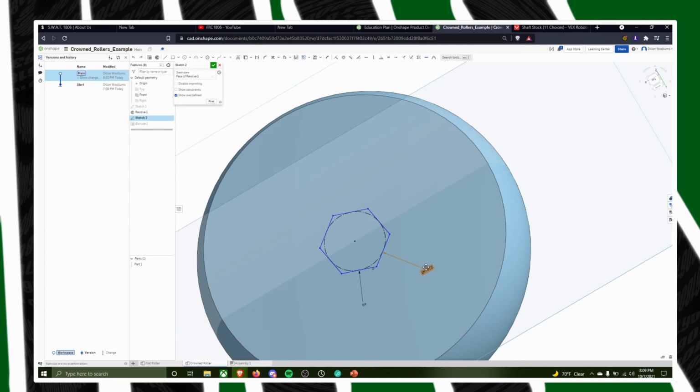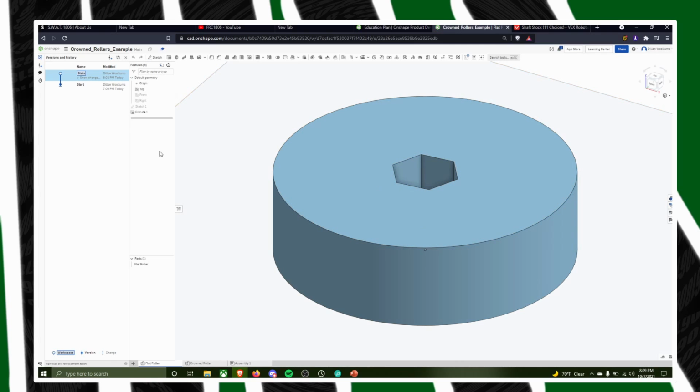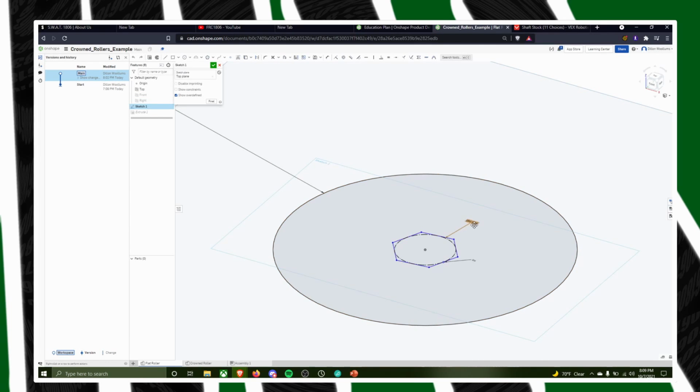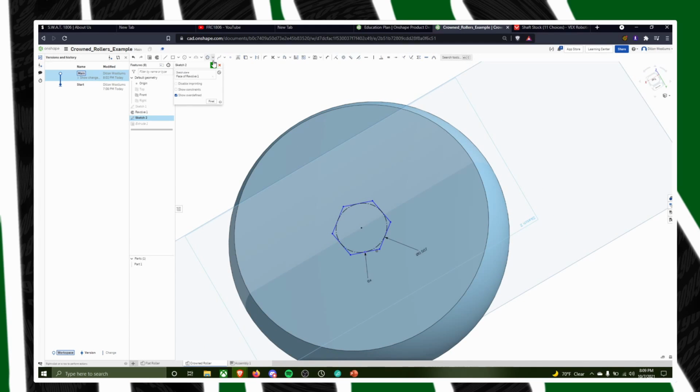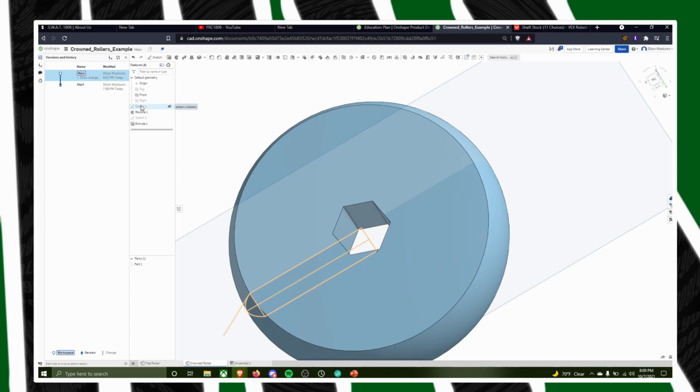Oh, and Coach Zinovich came back with 0.507 on that, because he seemed to want it to fit a little bit tighter than what I was defining it as. And then hit check mark, and it reapplies the extrude. So one thing to note is the features are in order. So if you go and update sketch 1, it reapplies through everything below it.